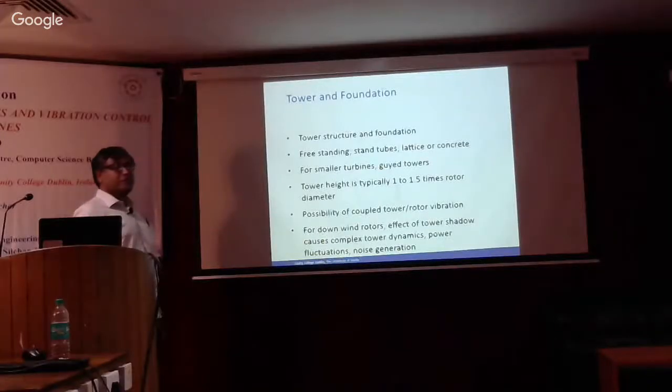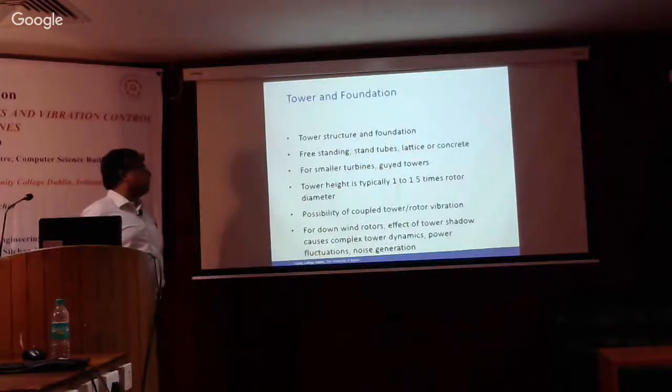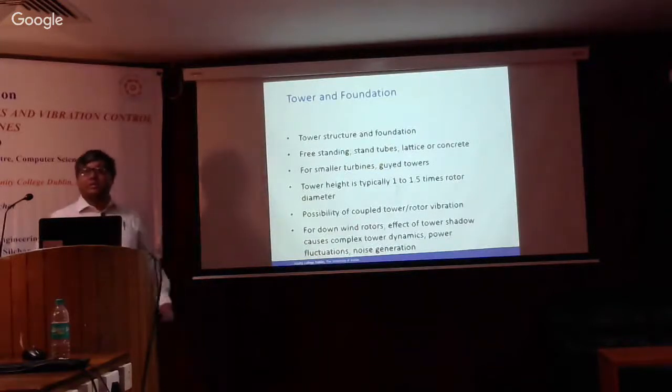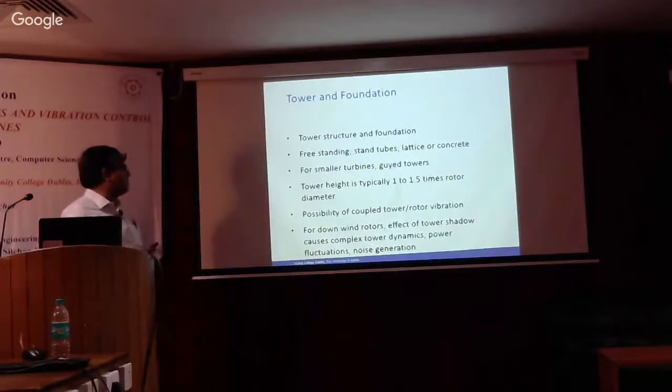The tower is normally a cylindrical tower and freestanding, and you can have a lattice or concrete tower as well, or composite towers. For small turbines, you can also have guyed towers that are connected by cables. Typically, the tower height is 1 to 1.5 times the rotor diameter.